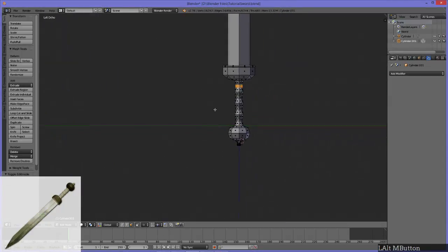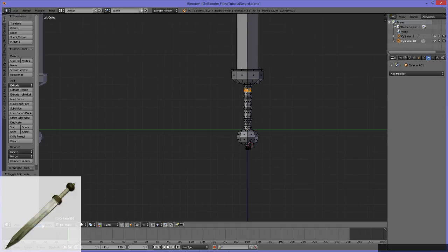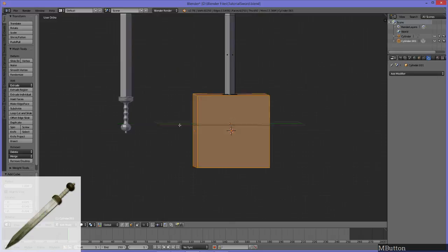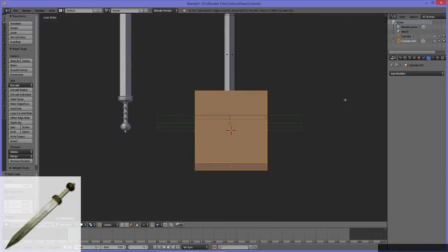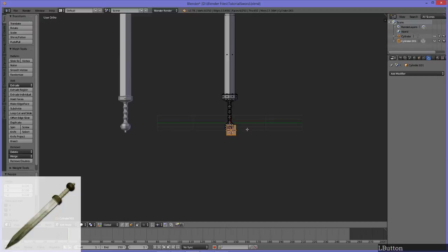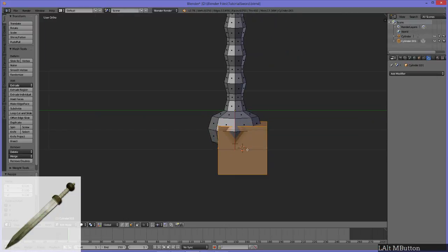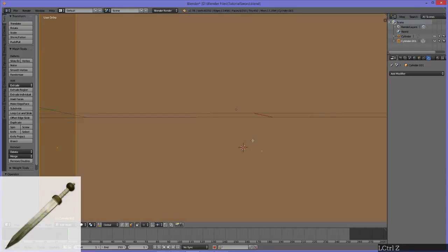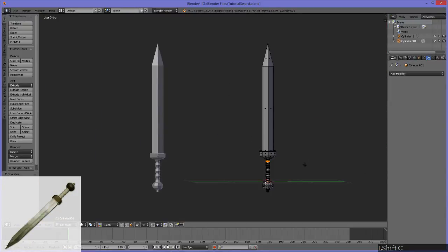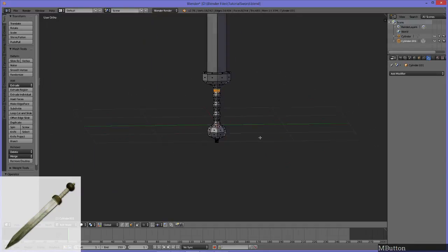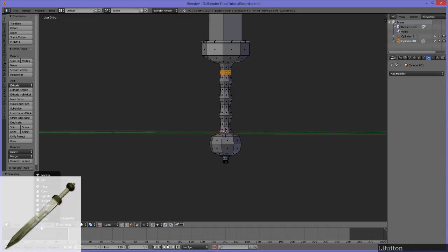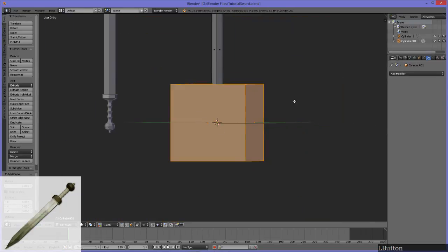So what we're going to do for this is we're going to append a mesh. So I'm inside of edit mode right now, so we're still in the same object. We're going to add a cube. Boom, there it is. It's obviously huge. Let's scale that down. Ooh, you see it added it where our 3D cursor was. I don't think I want that, so I'm going to undo that. I'm going to press Shift-C to recenter my 3D cursor, and that's a fine spot. Now let's re-add that. Cube, scale.